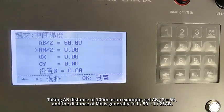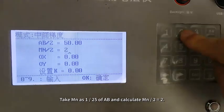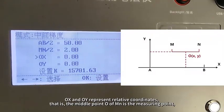The distance of MN is generally 1/50 to 1/25 of AB. Take MN as 1/25 of AB and calculate MN/2 equals 2. Ox and Oy represent relative coordinates, that is, the middle point O of MN is the measuring point.